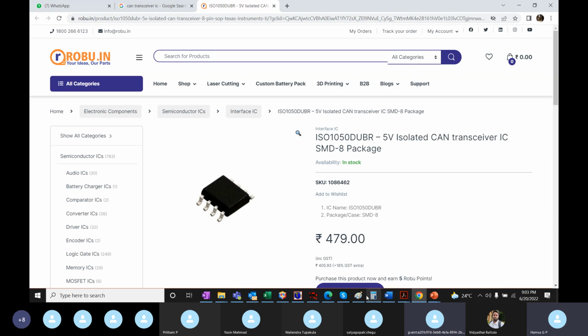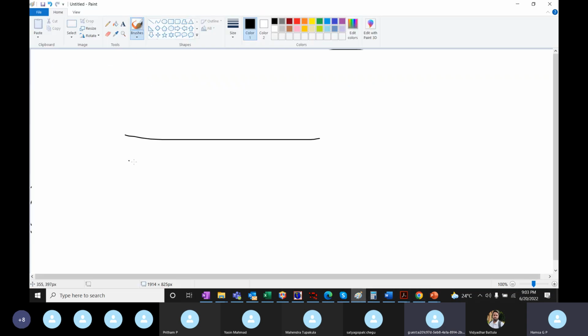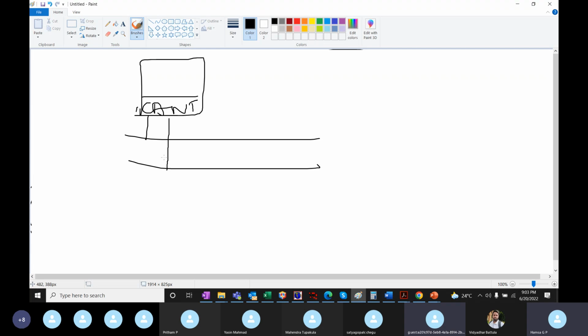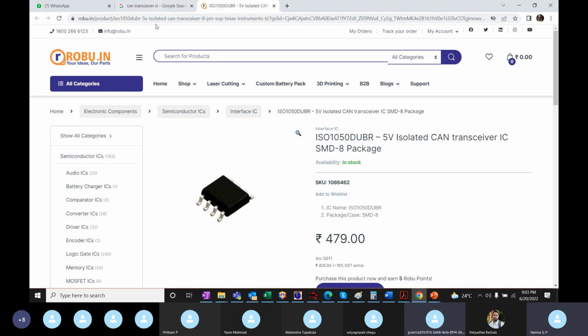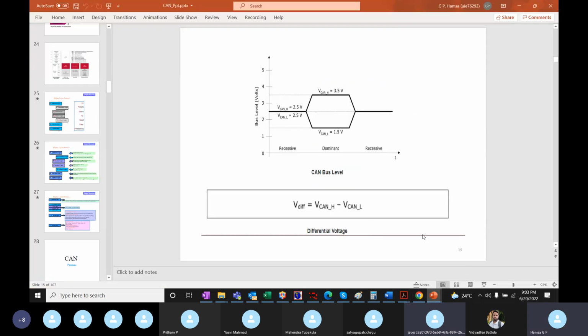So now, according to your question, you are saying we have a CAN transceiver in the ECU. Its job is to take the input from the bus and give the output to the bus. It can operate for both sending and receiving. That's what we have discussed, right? It converts voltage to binary and binary to voltage. Okay, so now your question is clear, I hope it's answered. Great. Okay, no problem. So moving on.